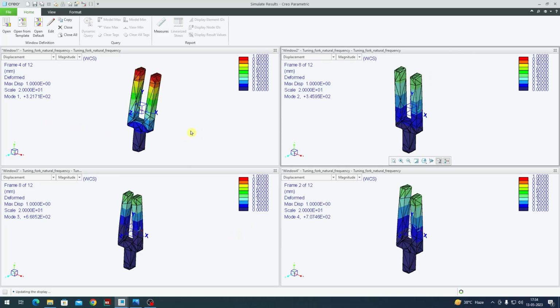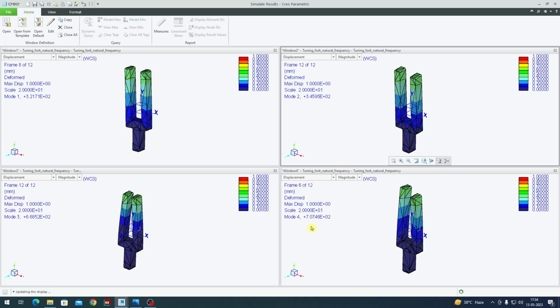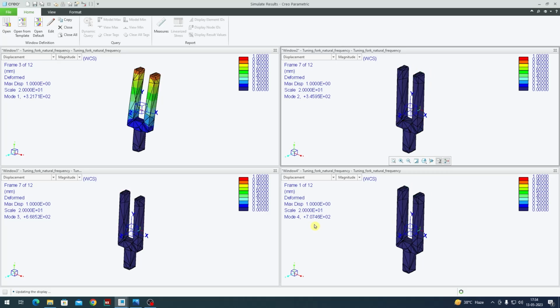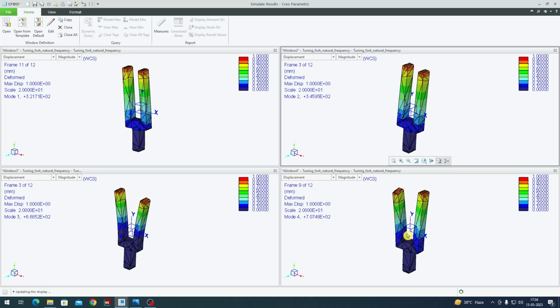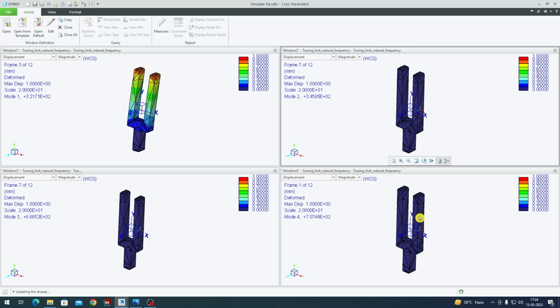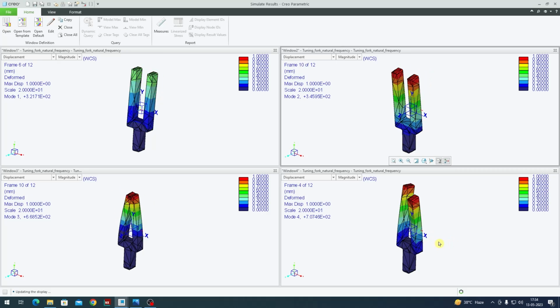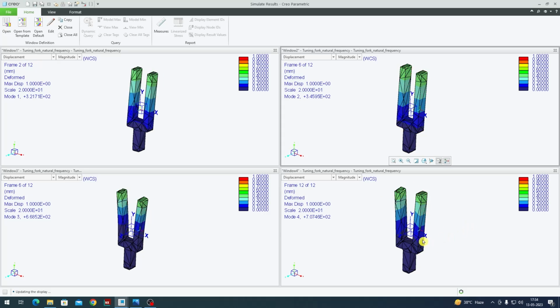As you can see, as the mode progresses into 1, 2, 3, 4, you will see an increase in the frequency. That means that you need more input frequency to see this kind of mode shape in a particular object. So your object is kind of stiff for these modes, so you need to increase your frequency in order to see all the modes in an ascending order.